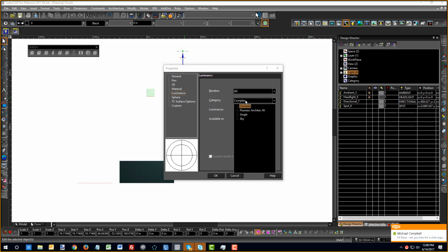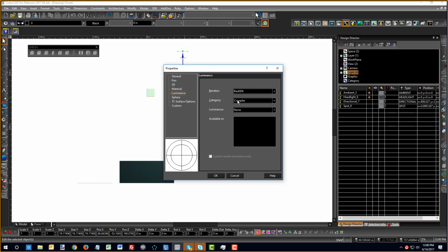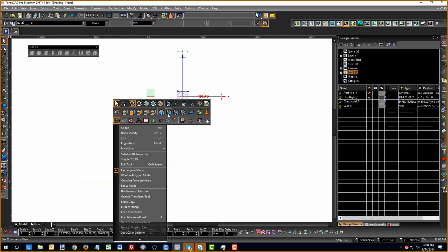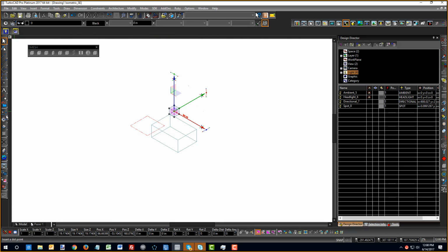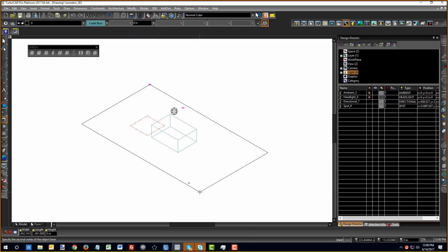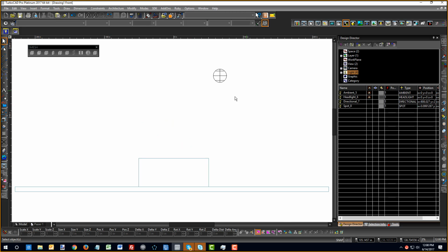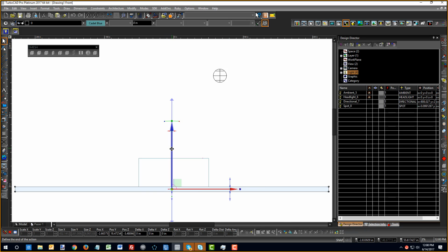So in the case of a single object in Red SDK mode here, let's just add a single point light. Whenever I'm doing this kind of thing, I like to draw another object down below, so you get a little bit of shadow here. So let's look at this from the side. I'm going to drop this down a little bit.